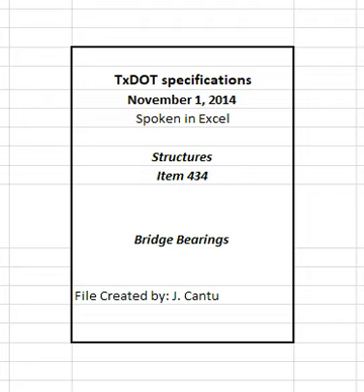2.3.3.1.3 PTFE. For expansion HLMR bearings, furnish PTFE materials that are pure virgin polytetrafluoroethylene fluorocarbon resin, unfilled. The finished materials must exhibit the physical properties shown in Table 1. Provide PTFE that is bonded to the top steel bearing plate of the HLMR assembly in accordance with TxDOT LRFD bridge construction specifications.